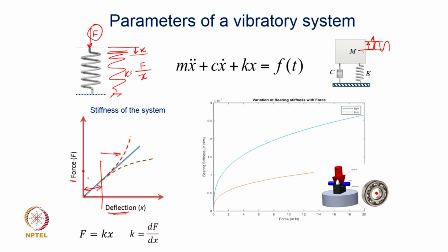That means, most of the times the amplitudes are well within a small amplitude range, and that is the reason why you would find a string attached to this particular equation which has been derived. This is based on the assumption that the amplitude of vibration is small, and that small has a lot to do with this particular range. Okay. And so, because small amplitude vibration pertains to this range of linear force deflection relationship, it is perfectly valid to assume a restoring force which is directly proportional to x, and k being constant, and therefore, the small amplitude vibration takes care of linear vibration analysis.